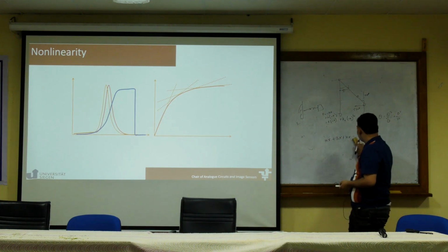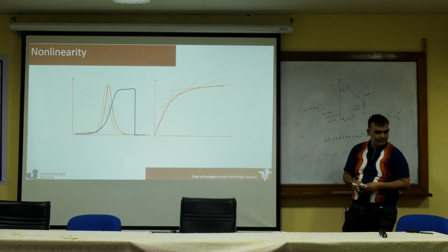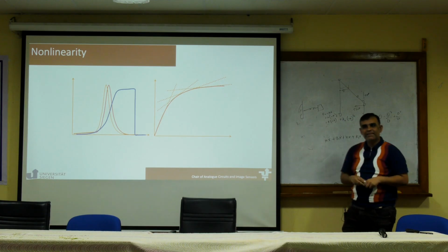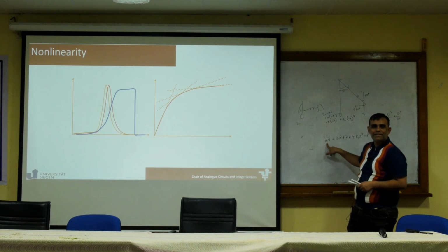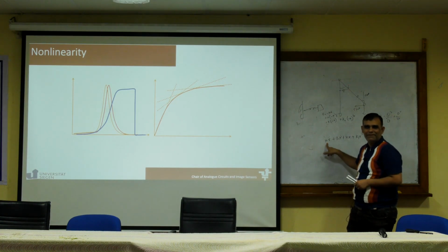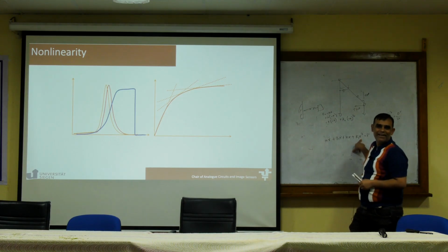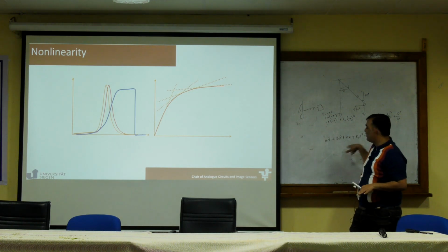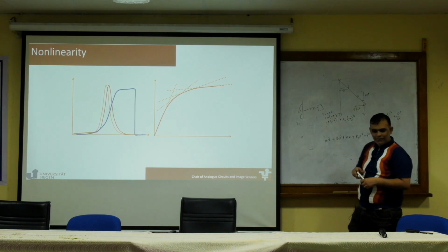So we now get a relationship something like this. Plus kx plus k1 x cubed is equal to some sinusoidal force. What will be the solution to this? So that part you can solve. Every maths course teaches you how to solve a second order differential equation. All I have done is I have added a simple nonlinearity to it. Just one cubic term, nothing else. I haven't done anything to the damping yet. Okay? How will you go about solving this?